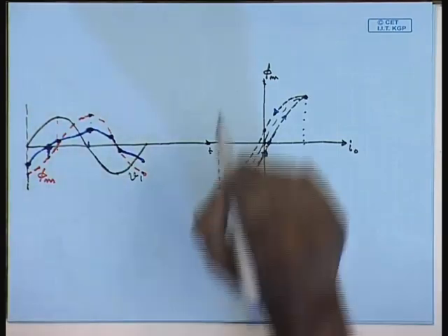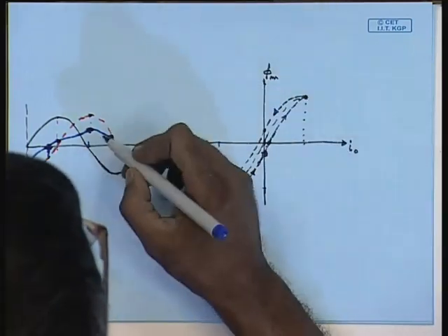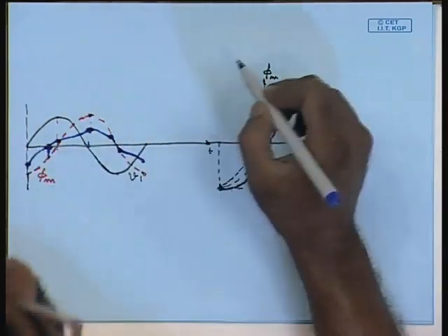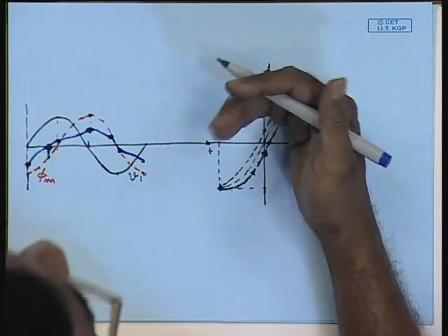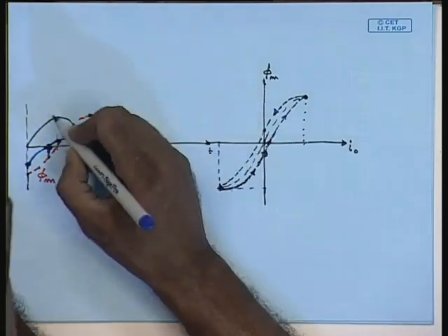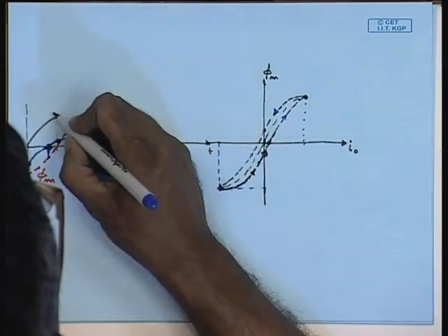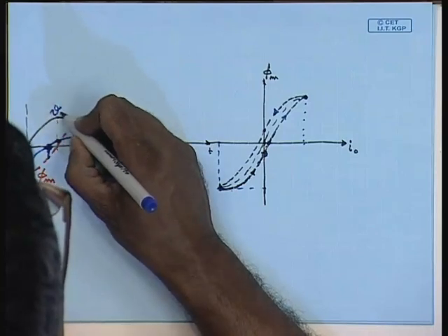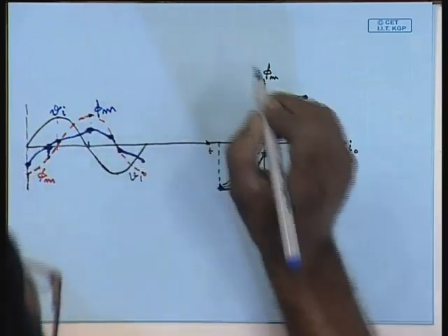Which is not sinusoidal. Although it is symmetric around the y axis, it is not sinusoidal, unlike the applied voltage waveform V1 or the flux waveform phi m.